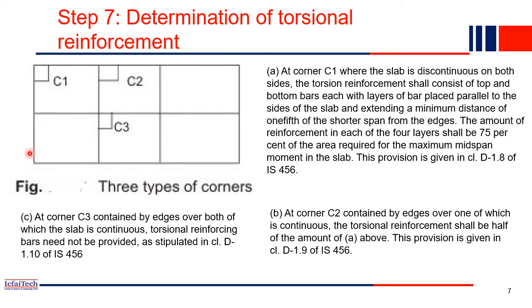So this may be a big plan of your building, where beams and columns will be there. This is one slab panel, this is another slab panel, and so on. Here you will find a total of 6 slab panels, and each slab panel will have a different design. Because if you see this slab, two sides are discontinuous.